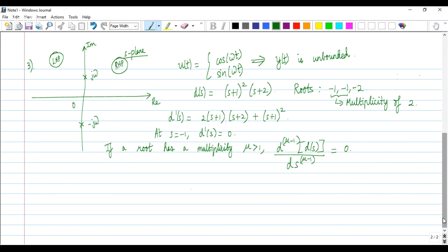And in connection to a set of questions raised on this, I reiterate that if you have non-repeating poles on the imaginary axis with all other poles in the left of the complex plane, obviously the inputs which result in unbounded output are the sinusoids whose frequency is equal to the magnitude of the poles, right? Of course, if the non-repeating pole is at the origin, then the step input would give an unbounded output.